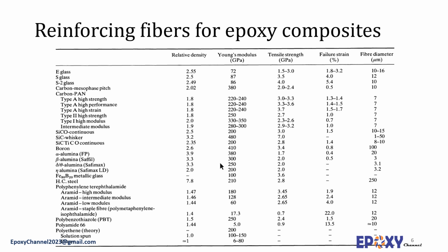Short or discontinuous fibers are not generally employed in epoxy resins because of their poorer reinforcing efficiency compared with their continuous counterparts. The mechanical properties of reinforcing fiber are the backbone of fiber composite technology. Compared to the matrix, the fibers have significantly enhanced strength and stiffness with lower densities. Typical mechanical properties of common reinforcing fibers have been presented here.